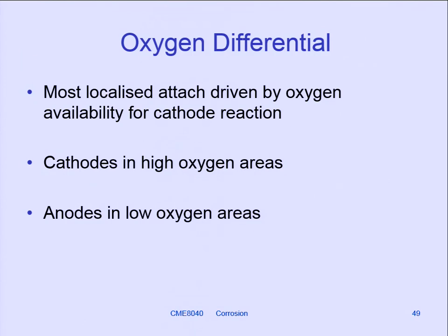This was part of the heating system for the bath, so the pipe came into the tank, which is a big tank of acid, went down to the bottom, and the pipe with the hot oil in it runs along the bottom, zigzags along the bottom and comes back out again. This bit we've got here is part of the section at the bottom. It's just cut out at the bottom and was part of the failure.